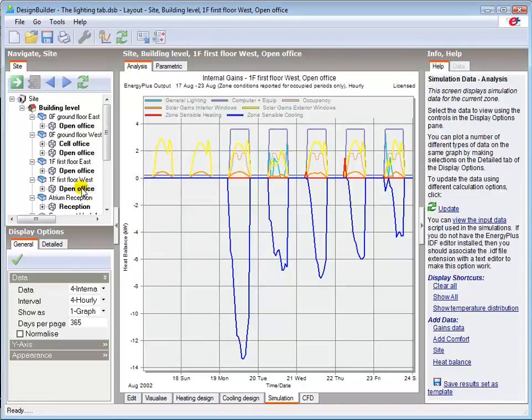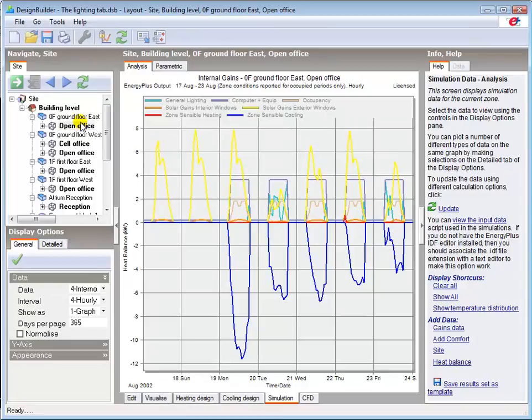You'll also notice here in the western zones that there's still an artificial lighting demand early in the day, when daylight levels are low, but the daylight controls have eliminated the demand in the afternoons. The converse is true in the east zones, when daylight levels are generally higher in the mornings. Overcast days have lower solar gain and daylight illuminance levels and therefore require more artificial lighting.